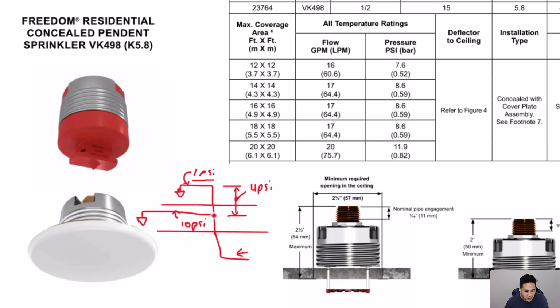Let's say this sprinkler head, which is at a lower elevation, you basically have 4 psi more at this point than at this point because of the height elevation. So let's say, I'm just going to make up a number. Let's say this is 50 psi pressure. The point right here would be 4 more than that, right? So you have 54 psi of pressure right here.